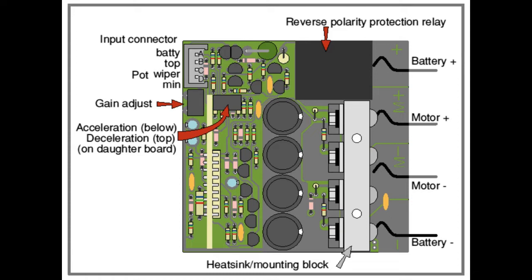The amplifiers were 24-volt versions, and I wanted to run initially on 12 volts. This was no problem, except that there was a 24-volt relay at the supply input to protect against supply reversal. My plan was to fit battery leads that were too short for reversal, so I simply shorted the relay contacts and cut through the relay coil tracks. I didn't bother to remove the relays.